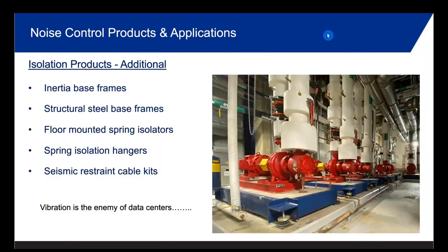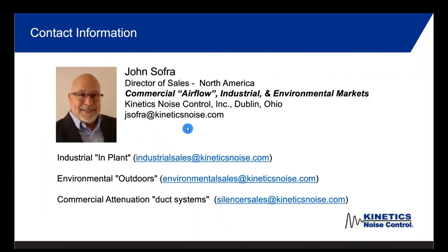The next thing is isolation products. This is actually a pump room from a data center. And you can see all the inertia bases with the isolation springs on them and the massive inertia bases to control the vibration here. Floor mounting spring system, spring isolators, seismic restraint cable kits for piping and ductwork. And then once again, vibration is the enemy of data centers. It's important in all data centers, but in some data centers it's even more important, such as a cellular data center or something that supports a hospital, different things like that, very important.